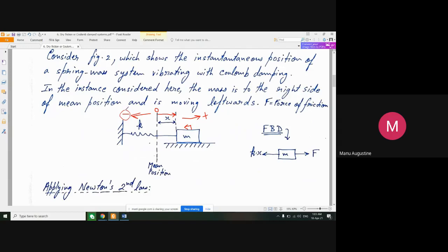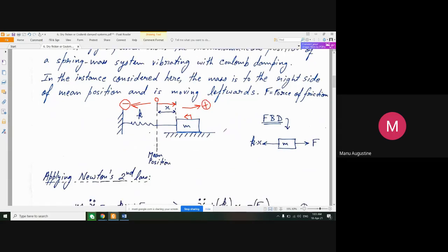Now this is very important, to declare a sign convention, because once the sign conventions are in place, for every vector that you encounter after this point onwards, you will have to put a proper sign on it. Because in the free body diagram, you will be looking at forces which are helter skelter. That means some forces might be rightwards, some forces might be leftwards. So some sign convention has to be in place. So this is how we put the sign convention in place.